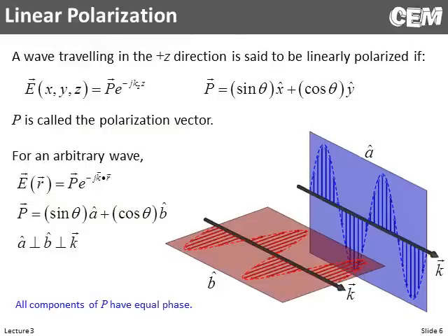So to put math behind it, we will start with linear polarization. The way we express this is we have an exponential term that's responsible for the oscillations. So that's what's describing your wave. The amplitude, if you will, is a vector, and we're going to call that the polarization vector. So somewhere at the beginning of your codes or wherever you're defining your source, we're going to calculate a polarization vector. So that's the direction the E field is pointing as it's propagating.